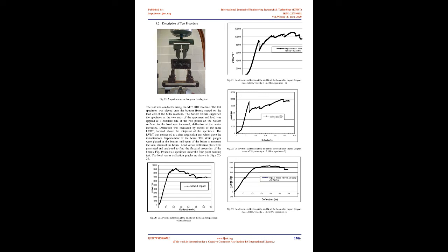After the impact test, the specimens were tested using a 4-point bending load to obtain the residual flexural properties of the beam. The details of the test are given in the next section. 4.1 Specimens Preparation. After the impact test, each specimen was glued with another untested specimen of the same size to recover the two skin sandwich beam specimen tested previously. The approximate specimen size is 4.75 by 10 inches. The loading configuration for the 4-point bending test is shown in Fig. 18.